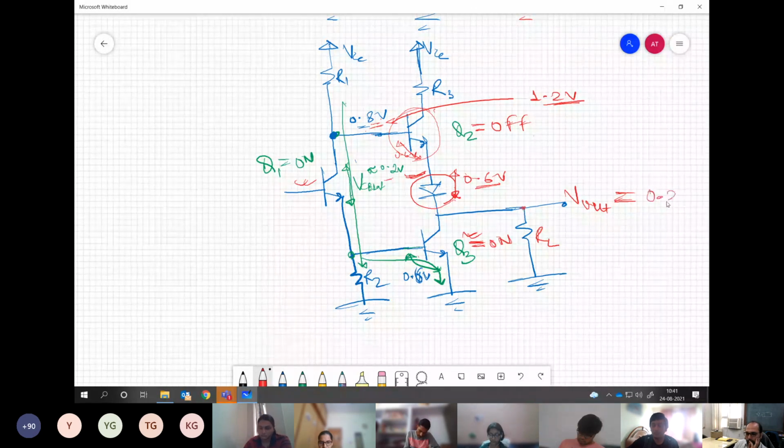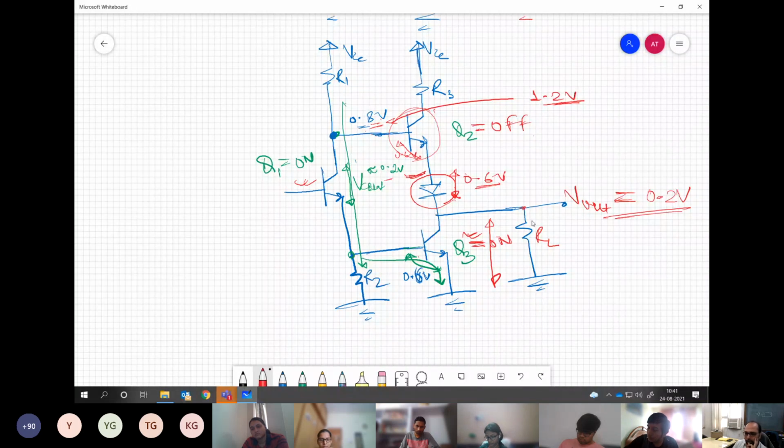Yes. That's the voltage across this resistance, right? VC SAT, that's all. So by default, irrespective of the load, the moment this transistor conducts, this is at 0.2, which means low, irrespective of what the load is. So that is the advantage of this TTL